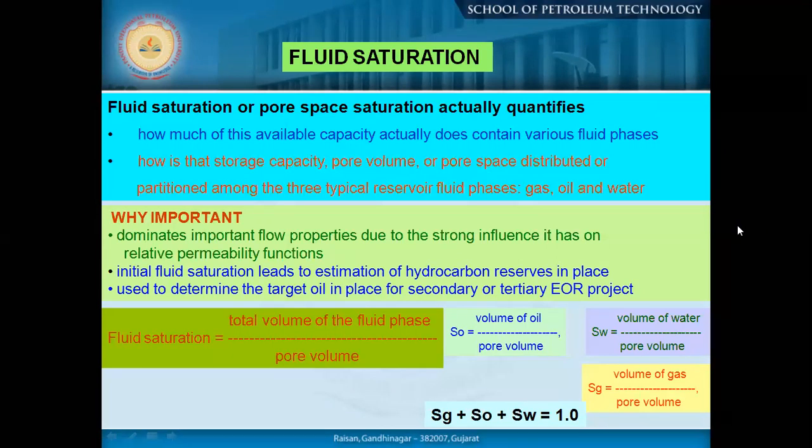If you remember the relative permeability graph, the relative permeability values vary with the variation of fluid saturation, isn't it? So when you are predicting the flow behavior from a reservoir, we should know the present saturation level.